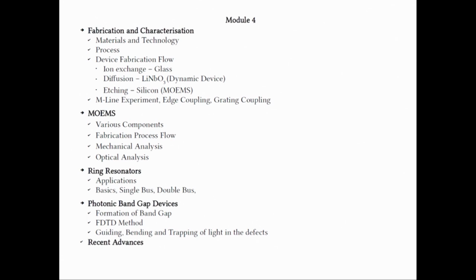Finally, we mentioned several other important emerging trends which we have not considered in this course, in particular photonic integrated circuits on active materials like gallium arsenide, indium phosphide, and so on. This is important in the future because these are the materials commonly used for optical engineering applications, and more importantly, you can make lasers and other active devices on these active substrates. That is the importance of using compound semiconductor devices.